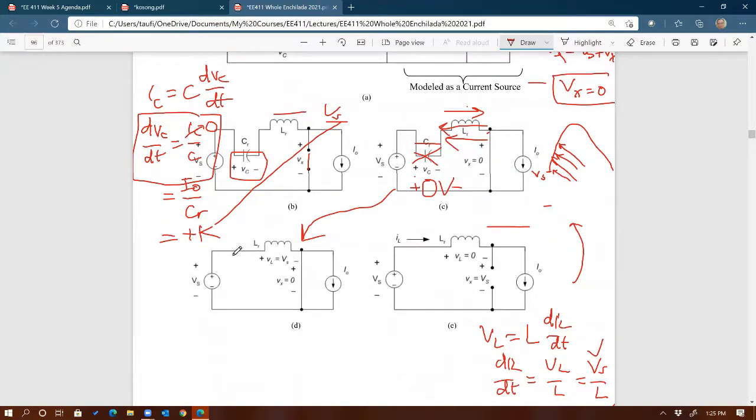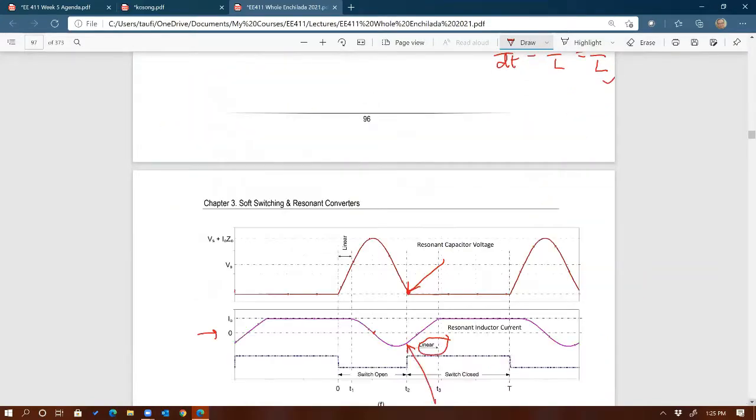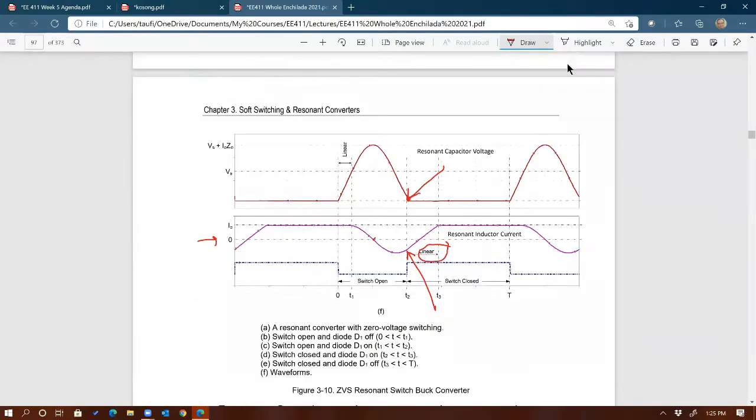As soon as the diode is conducting, then we're going to turn that switch on right there. Now you have two sources, right? Any question on that? So now we are turning on the switch at 0 voltage right here. You see this pulsing, the pulse that I have there. So right after the diode is conducting, I turn the switch on at 0 voltage.